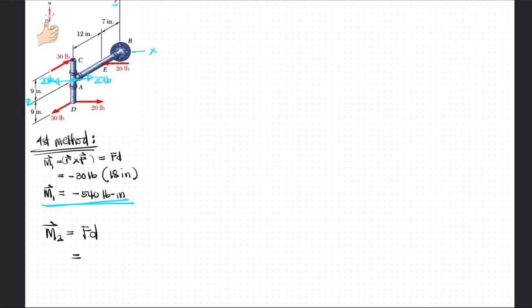So, positive 20 pounds times the perpendicular distance between these two forces, which is 12 inches, is equal to 240 pound-inch. So that is M2.